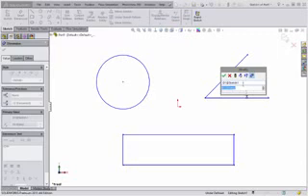You'll learn more about the way sketch dimensions can be referenced and utilized throughout this course. For this example, I'll go ahead and name the dimension and then type in the desired size. I could also use the thumb wheel or arrows to enter the size if I wanted. When I'm ready, I'll click OK to complete the dimension.